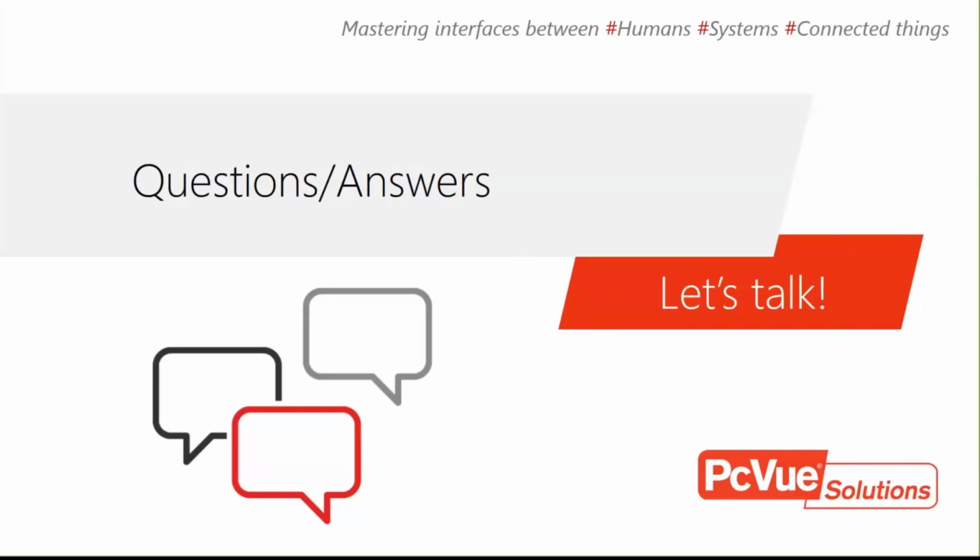Okay. Last question, maybe it's still about the LoRaWAN gateway. Fabien, do you know if it's possible to get the timestamp from the device using the LoRaWAN gateway, or is it not possible? With LoRaWAN, we can do it, but we need to create another variable, in fact. We have a variable for the value and a text variable to display the timestamp. Okay, so there's a way to do it anyway.